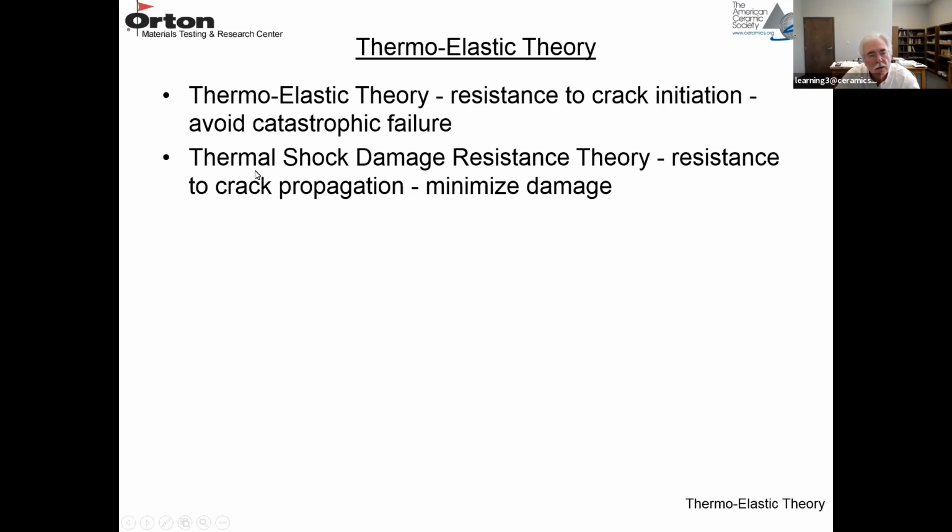In the thermal shock damage resistance approach, you allow cracks to grow, but you make the crack growth more resistant. So you build in a resistance to crack propagation, and you minimize the damage. You allow damage to take place, but you minimize it.